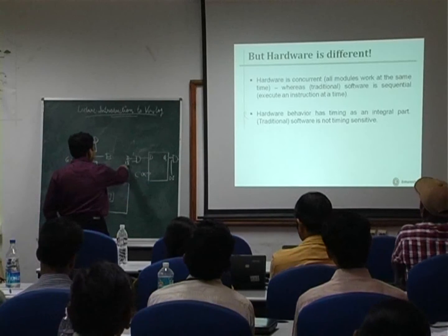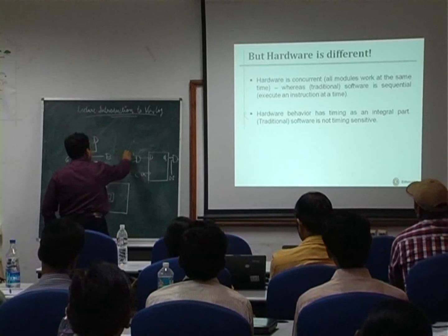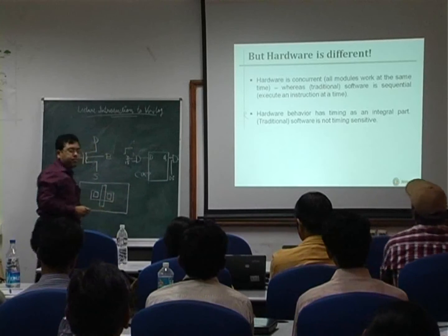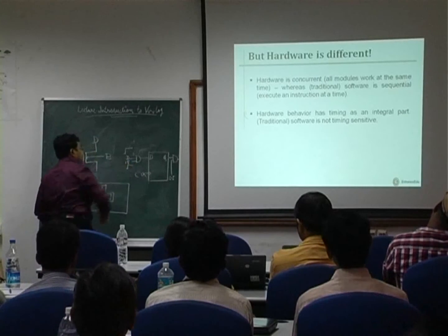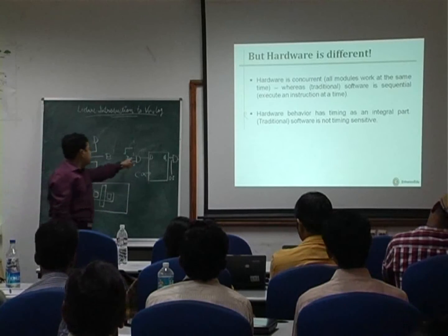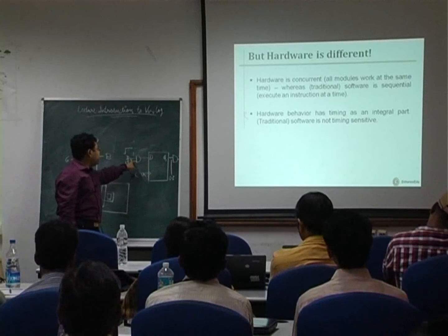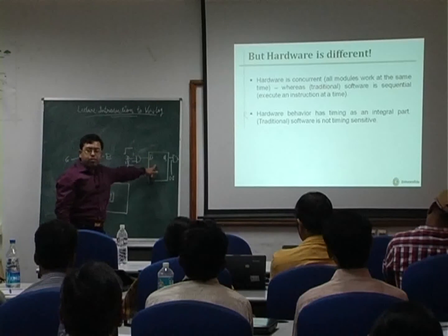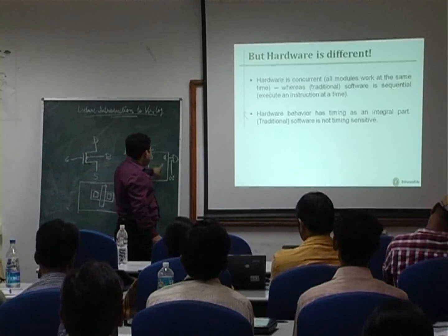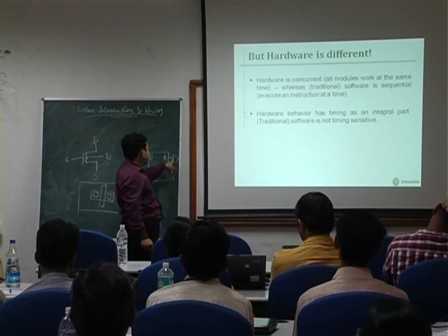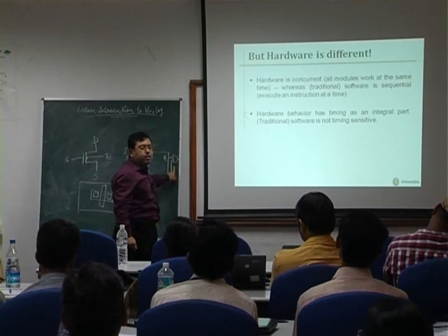Then we have to ensure that a little after this D gets high, we also assert this input enable line so that the input D reaches this D input of the flip-flop. And then in order to get the output, we have to assert this output enable line.